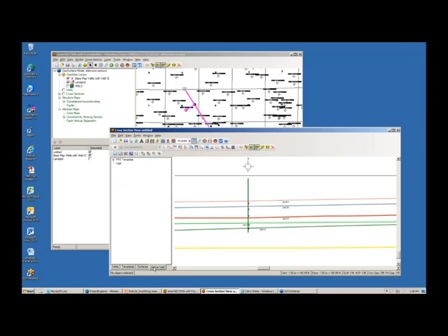Finally, and I think most importantly, is the Active Well tab. The beauty of the Active Well tab is that you can get the Select tool, click on any well in your cross-section, and instantly see all the available data for that well. So in this case, we have some curve data. If we had a raster log image, which I'll show later on, underneath log images, you would see all the different log images listed. More importantly, all those Prism templates you've built over the years and put in your project folder are also instantly available to you so that you can bring in any template that you're used to using to display your curves.